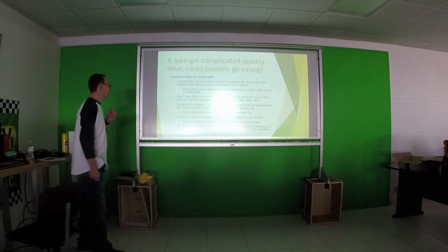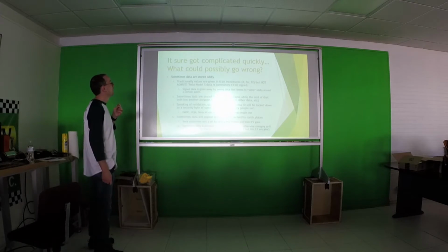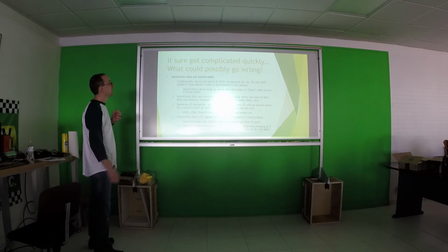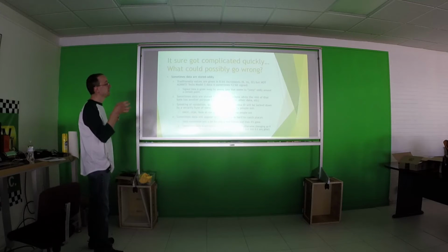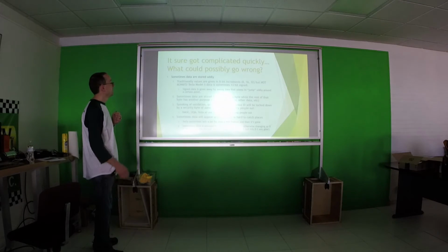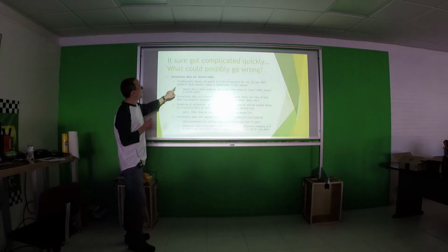There are various things that could go wrong or complicate things. One thing I mentioned is that a lot of times you want data found in 8-bit increments, so that when you look at the bytes, it's all packed neatly in 1, 2, or 4 bytes. That's not always the case. In Tesla, sometimes they use 13-bit signed values, which is complicated when you look at the bit patterns.